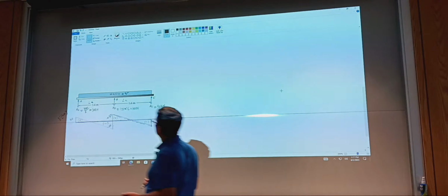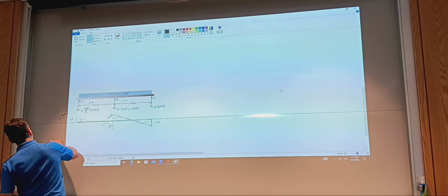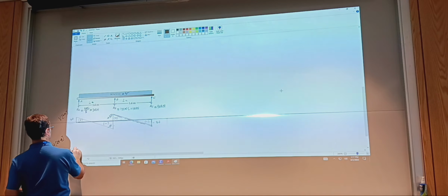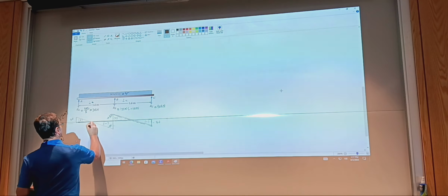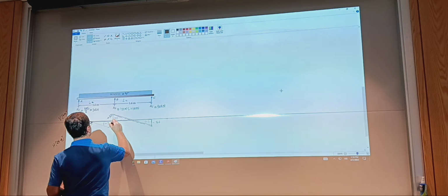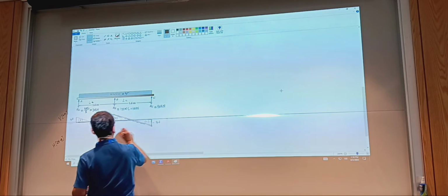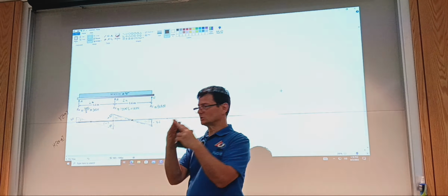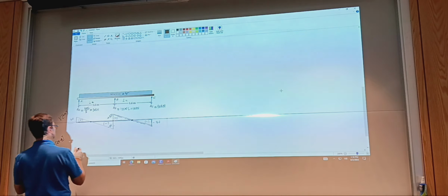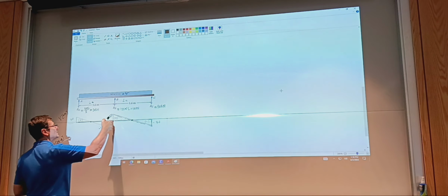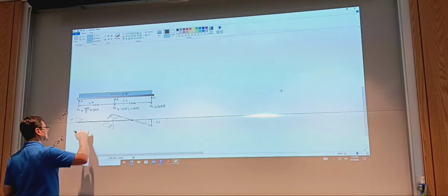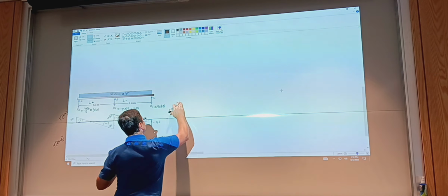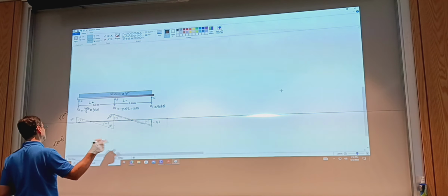Okay? And I can draw the moment diagram. The moment diagram, M, will be in kilonewton meters. And I'm expected to have, so I see 0 here. This is a smooth maximum or minimum. This is likewise smooth. And here I have an inflexion. The tangents left and right are non-zero and not equal, so yeah, it's a cusp. It will look probably like this, or maybe inverted. Actually, it looked inverted in the appendix.